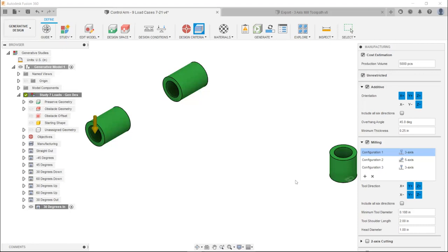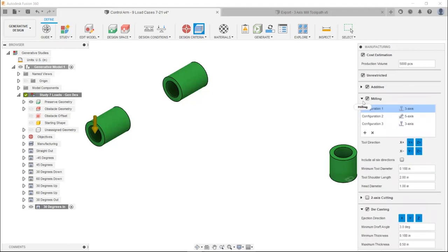So for example, if I'm milling down here, and now I need to mill this pocket out, if it's a 3 axes mill, I'm going to physically have to take that material out of the vise and turn it. So that would be a second setup. With the 5 axes, we could just flip the material and then I could cut it. So that's an advantage to 5 axes. And then again, I'm defining the tool direction, and then the tool diameter.